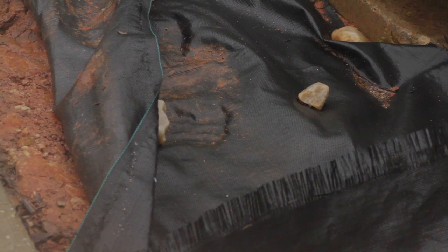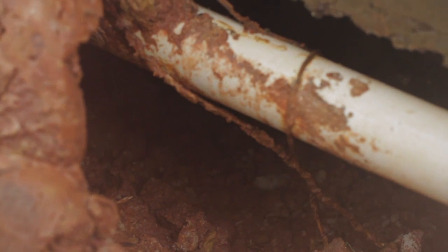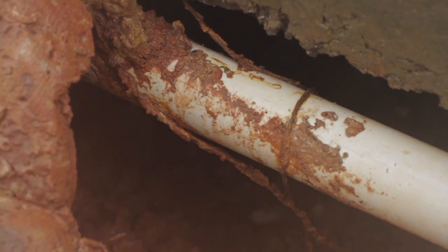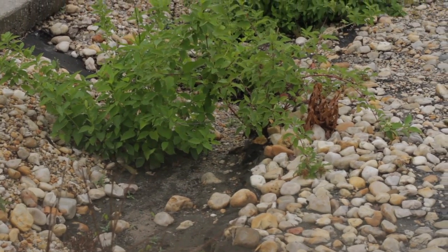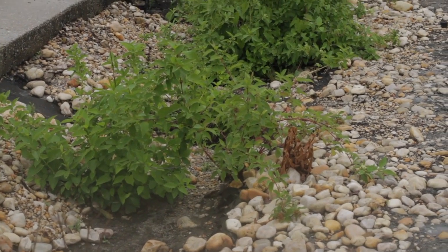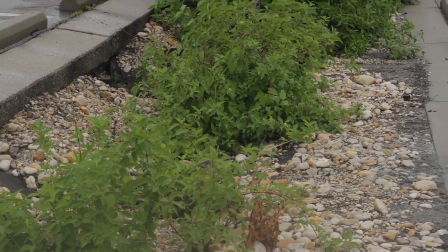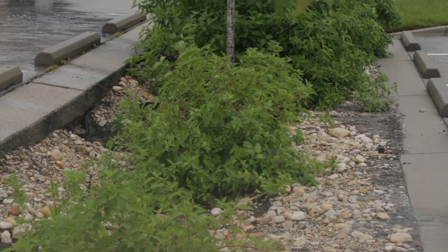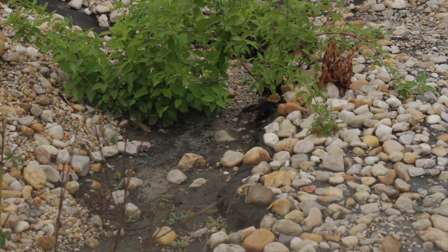Here we're at a bioretention facility that got some problems, we'll say. And it's important to identify what the problems are when you see them in the field. Some of these problems were driven by the design. One of the more challenging things with designing bioretention, because it is a parking lot island, it is in the middle of the site. Elevations, the grades that were designed on this particular site, leave a little bit to be desired, because on the side where I'm standing, it's about 1.5 feet lower than the opposite side of this parking lot island. That grade difference is fine, except the bottom of the bioretention facility is losing not only the gravel due to erosion because of the overly steep slope.